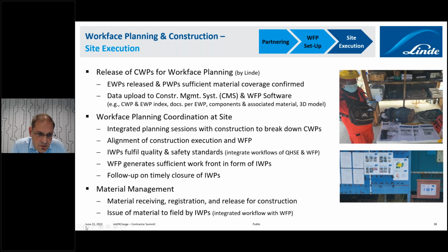But I think it's really important that we also set up the processes at the site, that material management is closely involved, that they have timely receiving of the material, that they put the data into the systems, that it's registered, and also formal release, so that we can have proper material coverage analysis, and also that the material is issued to the field, to the supervisor, IWP by IWP. So that's very key, to have integrated workflows with workplace planning for material management.